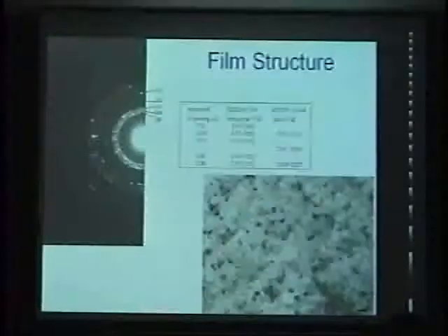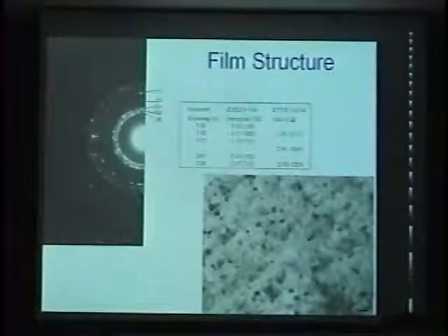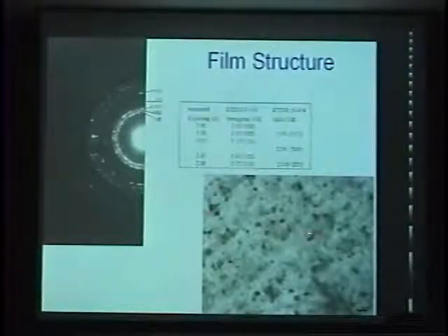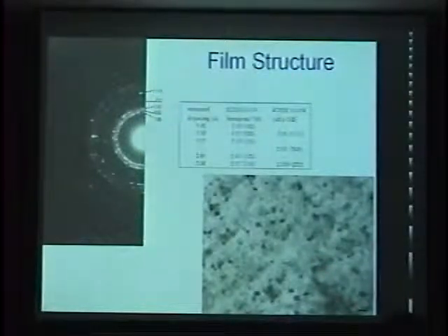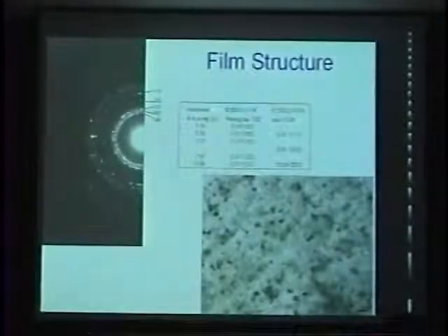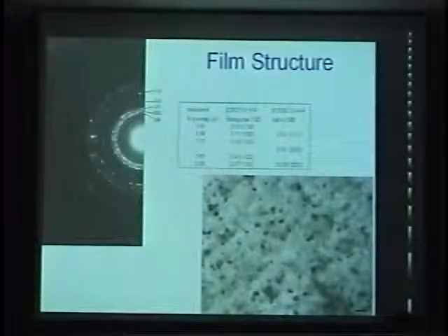So in this process, you actually have two processes competing. You have this surface CVD type of process, but you also have this homogeneous process like particle sticking. So what kind of film do you get from this type of process? Essentially this is quite a low-cost, cheap process. What you get, this is a TEM image. You see these are actually nanocrystalline films, and this normally shows a hexagonal cadmium sulfide structure. So essentially, what you get from this process is nanocrystalline thin film.